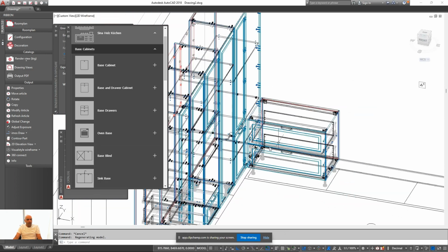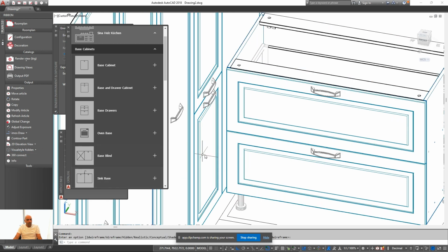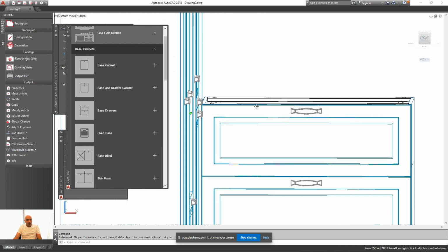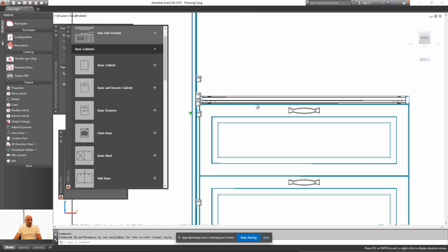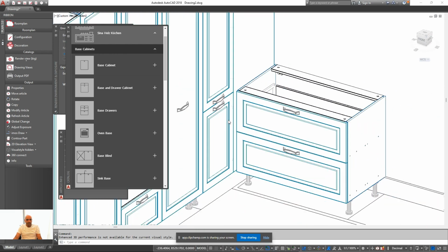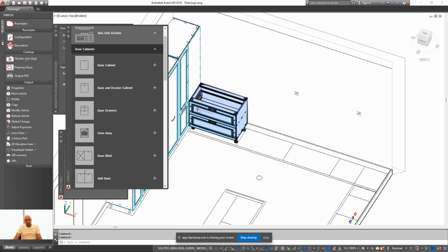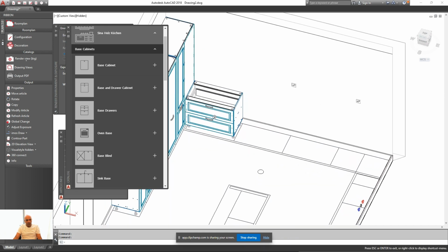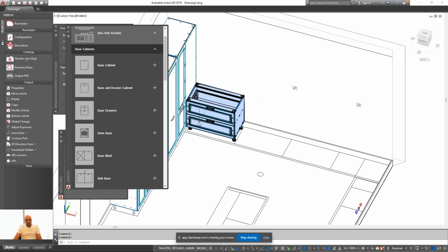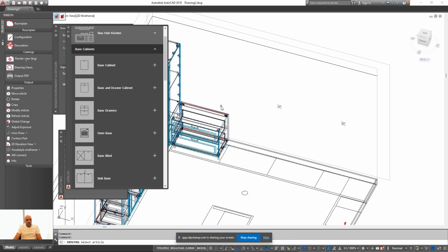Okay, here there is a point that we should consider. If I want to open the drawer, you see that the handle is having an interference. So instead of 3 centimeters, I should have more gap over here. I will adjust it.